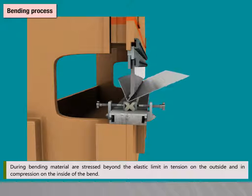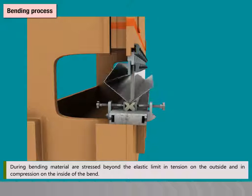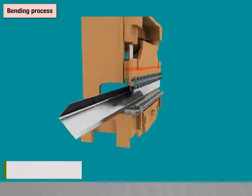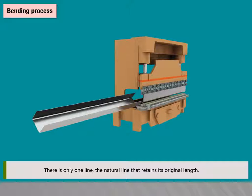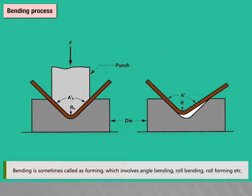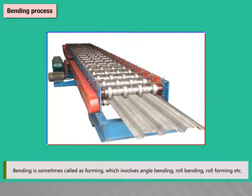During bending, material is stressed beyond the elastic limit in tension on the outside and in compression on the inside of the bend. There is only one line, the neutral line, that retains its original length. Bending is sometimes called forming, which involves angle bending, roll forming, etc.